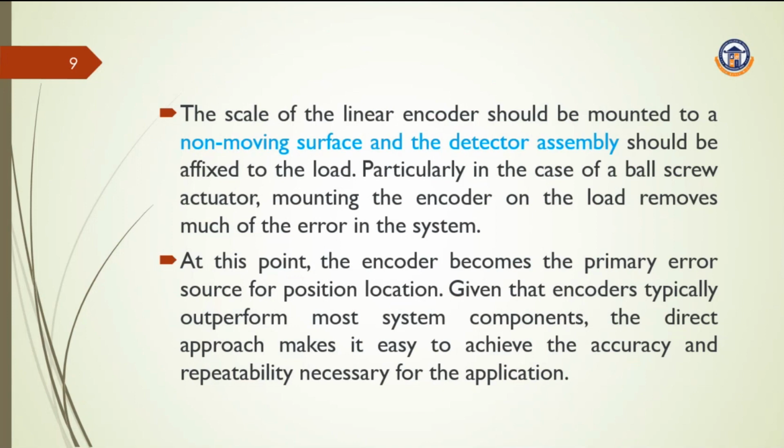So particularly, for example, in the ball screw actuator, mounting the encoder on the load removes much of the error in the system. Here, the encoders typically outperform most system components, and the direct approach makes it easier to achieve the accuracy and repeatability necessary for application requirements.